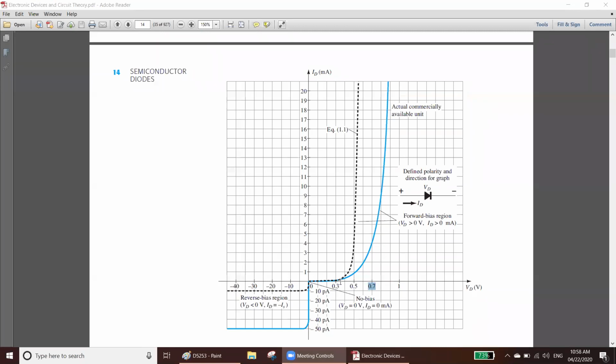Got my point? In case of germanium, see, when your voltage was 0.3, the current is significantly lower. When your voltage is more than 0.3, your current is rising. This one, the black one. In case of silicon, before 0.7, the current is lower because it is flat, like this. After 0.7, it is rising, like this. So this is the forward bias characteristics curve.